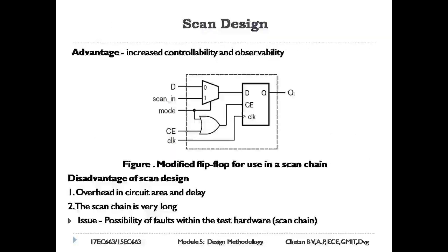Modification of registers to allow them to function as shift registers can also be automated. One approach is to design and synthesize the circuit normally, generating a gate level circuit with flip-flops implementing the registers. Then, as part of physical design, a tool can substitute modified flip-flops that have a shift mode, as shown in the figure. The circuit is placed normally. Finally, during the routing step, connections are made between adjacent flip-flops to form the shift register chain.